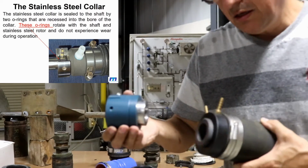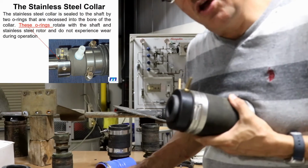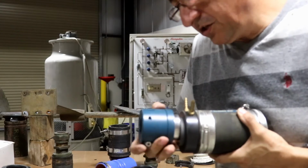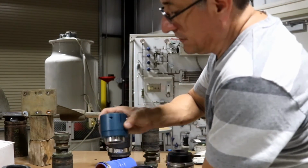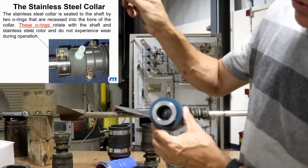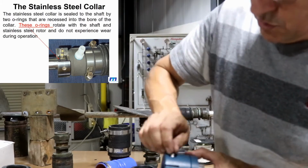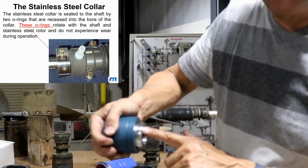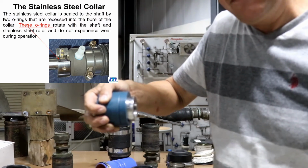This one is installed on the stuffing box. It's not moving, and this one is together with the shaft. This is spinning at the speed of the shaft because it's bolted on the shaft. This collar has 2 O-rings, like the O-rings on the screen, and this plastic element, when you tighten this one, the shaft will be together with the collar, and the collar will be spinning at the same speed of the shaft.